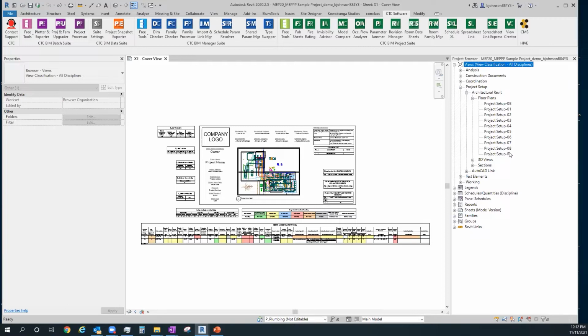It is an actual Revit project, inclusive of all work sets. All the Revit links and things like that are all inclusive in there already. So you don't have to go in a starter project and delete levels and copy monitor. We actually take these levels that are existing here and turn those into our real levels to match architecture typically. And then from there, any levels that we don't use, there's a Dynamo script that lets us purge levels that we're not going to use.